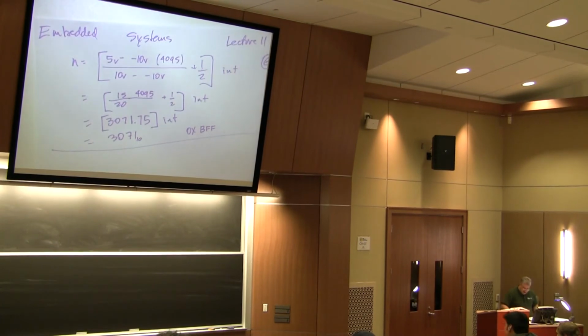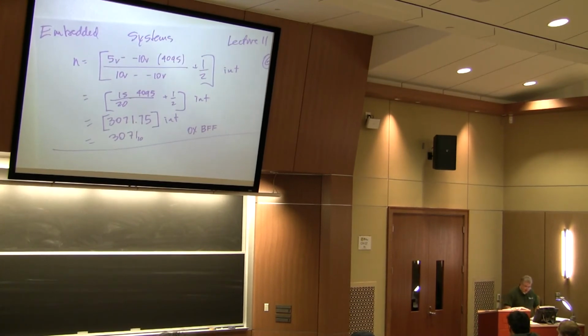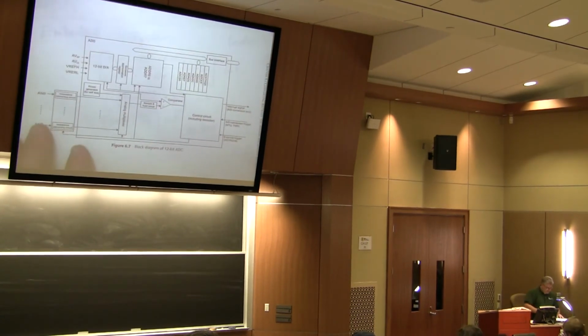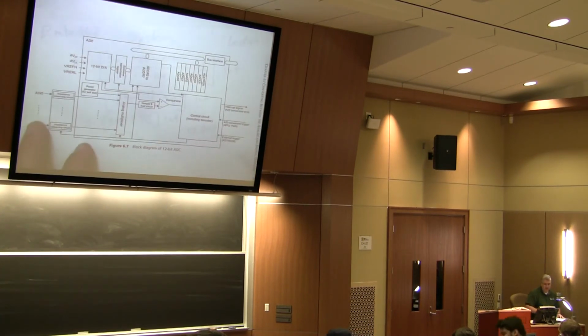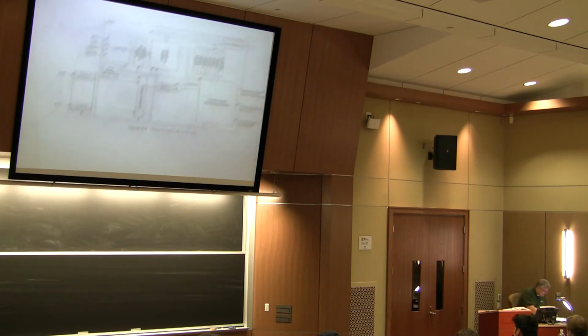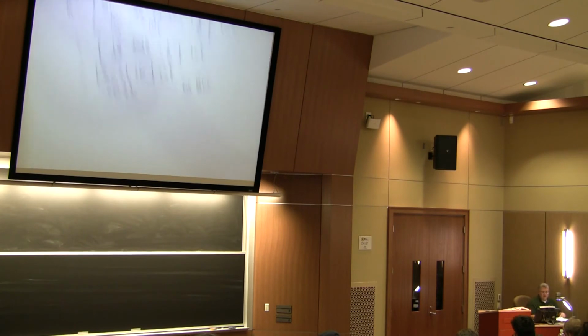Now, what I would like to do is to talk a little bit more about, now that we have our concept of ADC, how are we going to use that? So again, remember in our circuitry, we have our control circuit, includes the decoder. I want to point out a couple of pins here that are important. Number one, the external trigger. If we want to do an analog to digital conversion in our microcontroller, what are the types of things that are important?